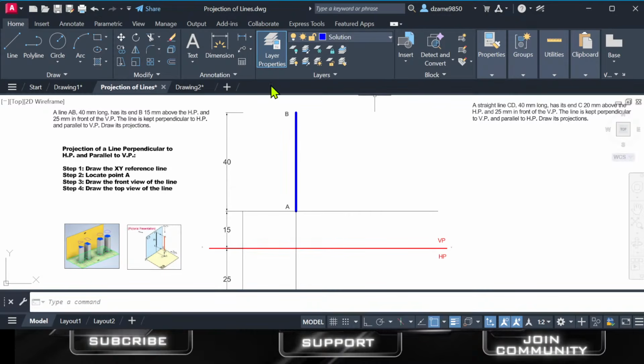Now, I will take you back to what we're going to do today, because in my case, I've just created some different layers for you. For example, as you can see here down, the XY layer is in red, reference line. Construction layer is just still light. Here it is as construction lines and also dimension lines. The solution layer, which is in blue, is thick and bold. I've increased that, we call the stencil, the line thickness.